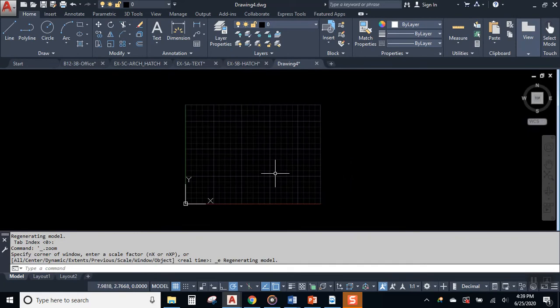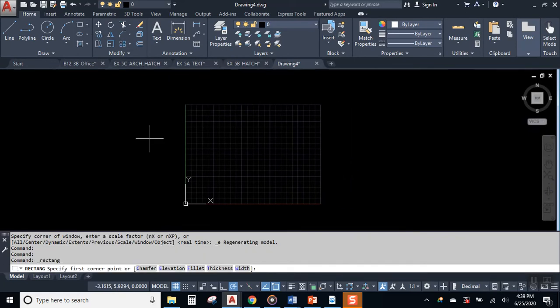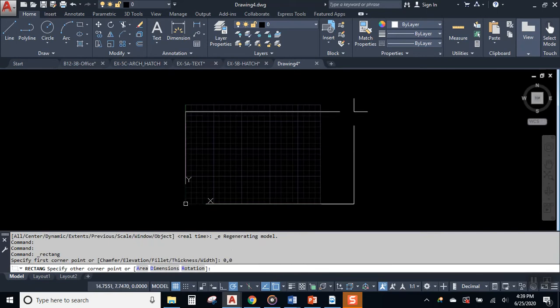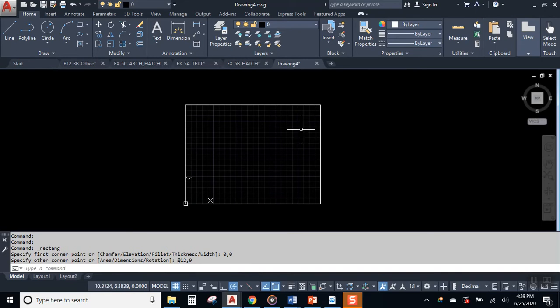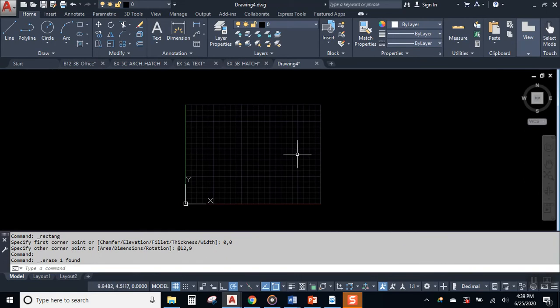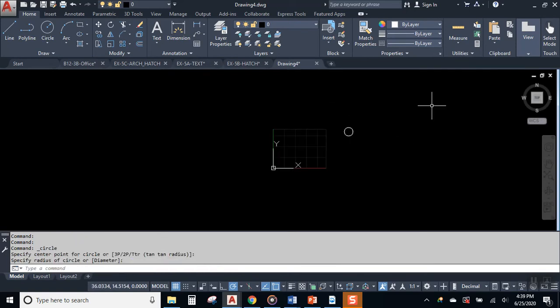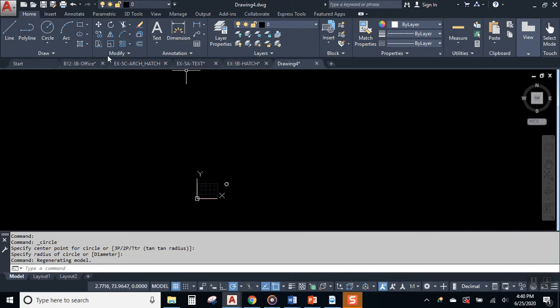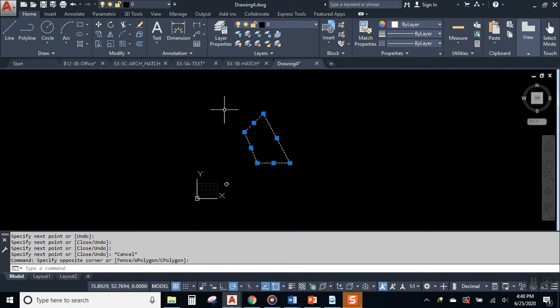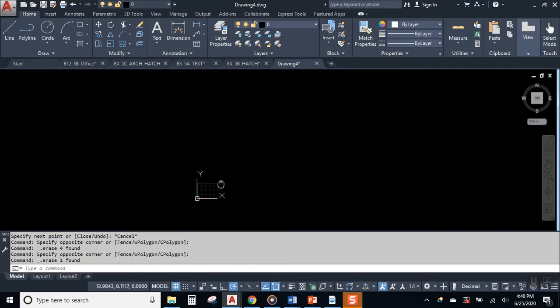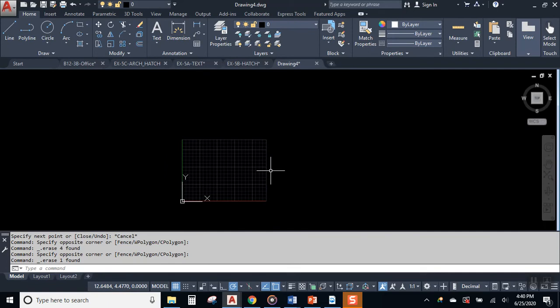You see a standard AutoCAD drawing, believe it or not, starts off and it gives you about 9 by 12. If I say go 12 over and 9 up in the Y, it's assuming you're going to draw something small. Well, that doesn't mean you have to draw something small. It just means it's planning on you drawing something small. Now, you can draw out here past the limits, but you know, sometimes when you're working out past the limits of the drawing, AutoCAD starts getting cranky and it doesn't do what you want it to do. So a lot of times, not a big deal, but sometimes it will slow you down and it'll trip you up and it'll be frustrating as heck.